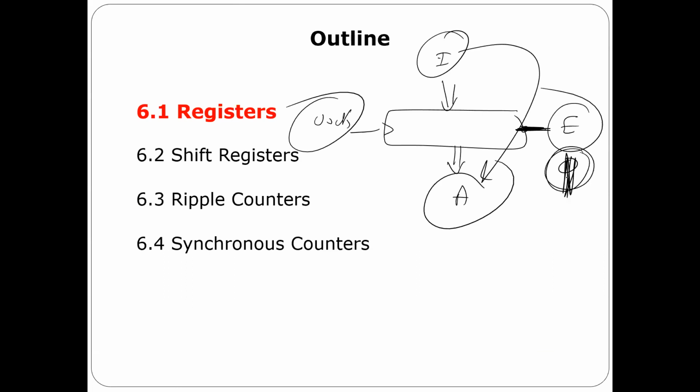Again, this gives me the flexibility to control, because if you think about a big system, there is a sequence of actions. I have to do addition first. After I do addition, now I have to load the register with this value, regardless of the clock. So that's why, to make it simple, I'm going to add something like an enable. At the time you want to upload this input, I'm going to make the enable 1.